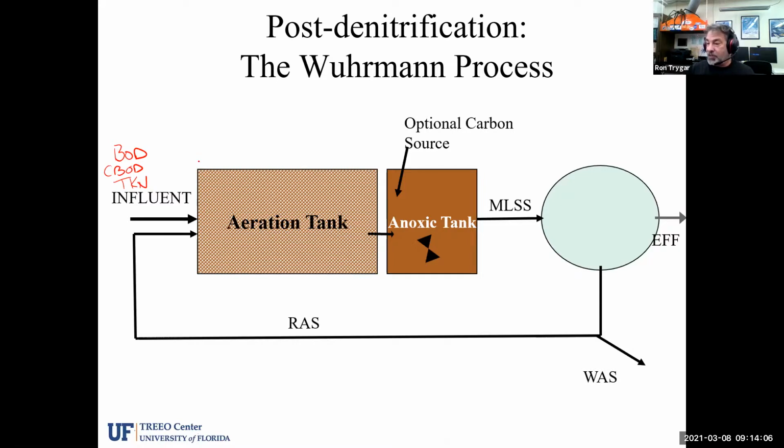So we're going to go essentially from NH3, and then we're going to go to NO2, and then finally to NO3. So that's the nitrate. That's what's happening in the aeration basin. The BOD is being used up aerobically because we have a lot of oxygen in here. So O2 is present, and we're actually using up the BOD and CBOD in an oxidative process.